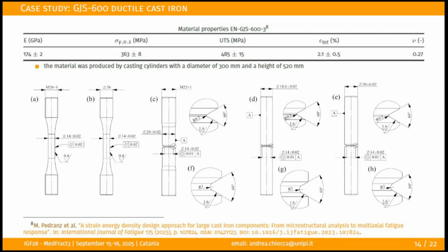In this case, the material is behaving completely differently. It's quite fragile from a fatigue point of view. Also, we have different geometries and different loading conditions. The method was calibrated using a blunt and a sharp notch of uniaxially loaded specimens under fully reversed conditions.